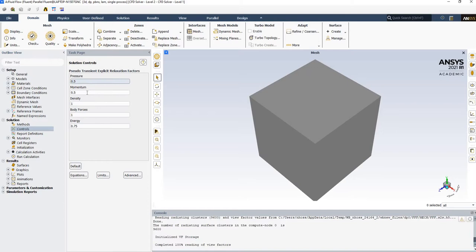they play with the relaxation factor because the air is trapped inside and there is a hot side of it. Air keeps recirculating, so it's difficult to get a steady state. So what they did was they reduced the momentum relaxation factor to 0.1. You can play with it, okay? That would stabilize, but again, the accuracy can go off, so be careful when you change these values. If you don't understand it, don't change anything in here.